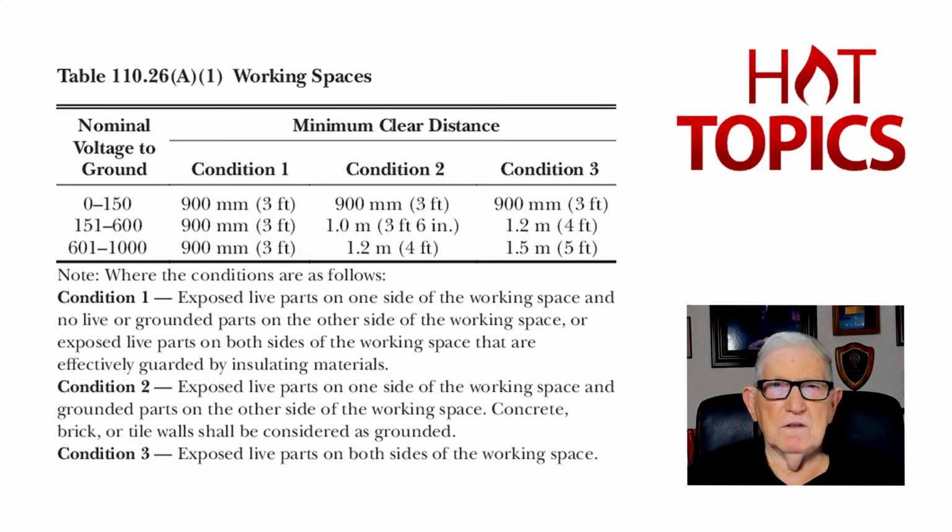And based upon the calculation in the Annex D, as in dog, to determine arc flash boundaries, the whole room may be an arc flash boundary. It may be 10 foot, 12 foot, etc. So no, this is just working clearances.